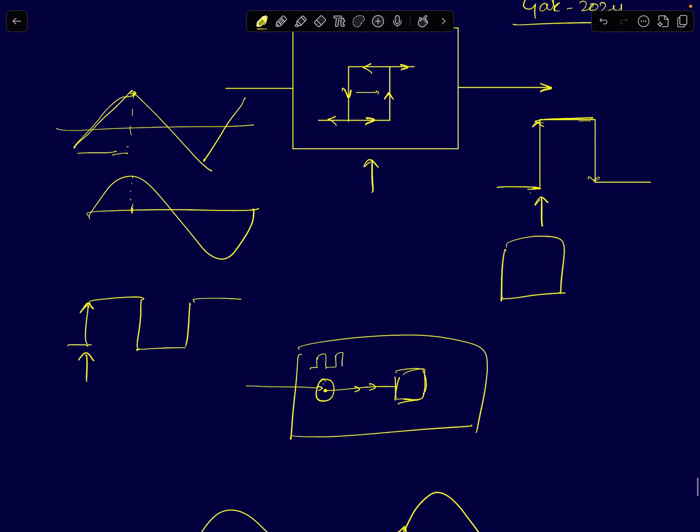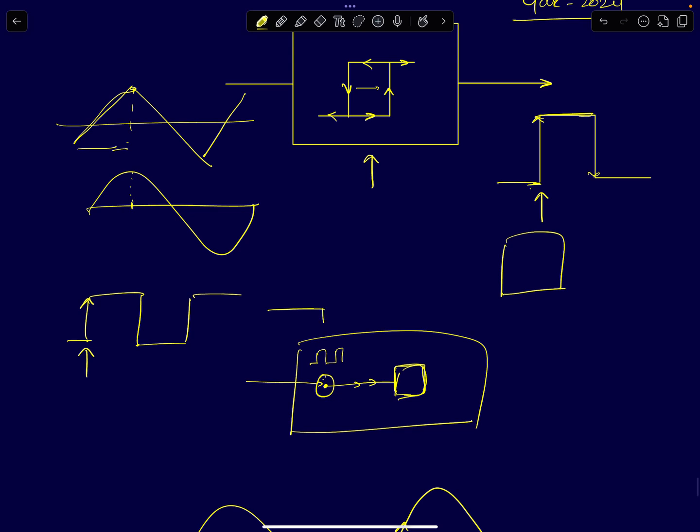Let's say you have a digital chip, which is soldered onto a printed circuit board, and on the printed circuit board you have a connector. It can be an SMA connector. If you don't know what an SMA connector is, don't worry about it right now. Let's assume that you are feeding a clock signal to this point on the printed circuit board. Then you'll have a copper routing that will route this clock signal into the chip.